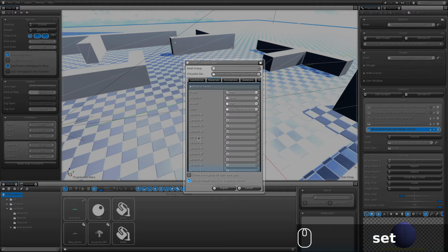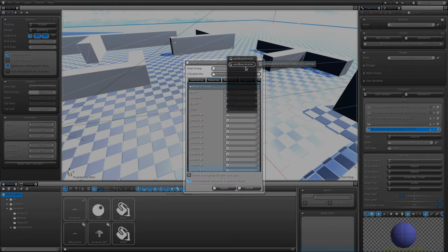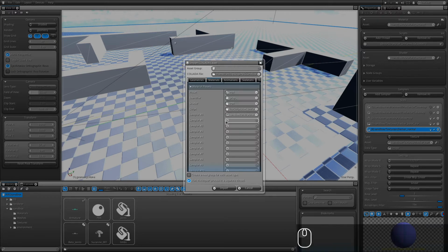Now, for our sampler, if we take reference from our textured material here, since that shader is expecting those sampler inputs, we are going to reproduce that. To change the type of asset that you want to link to the preset, simply hold Shift and then click. We have two cube maps here, so I hold Shift and press twice to access the cube map, and I'm going to reproduce basically what I have here. I have the irradiance that is set here. Once again, another cube map, so I am going to click on radiance this time.